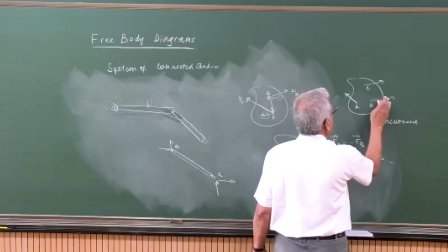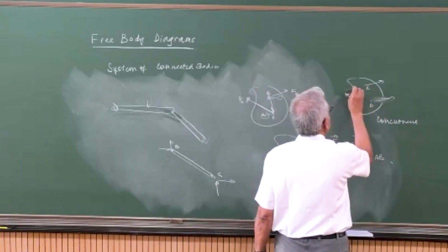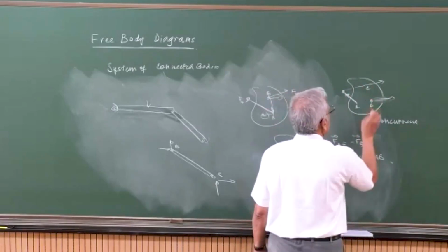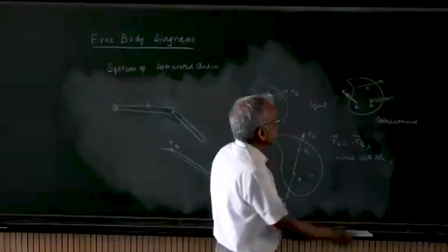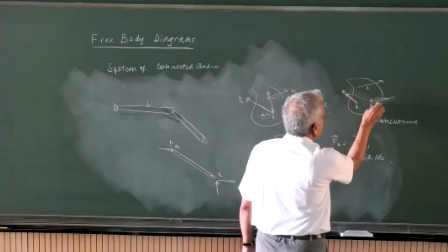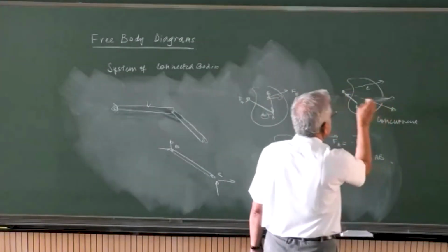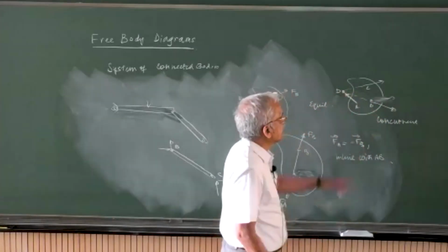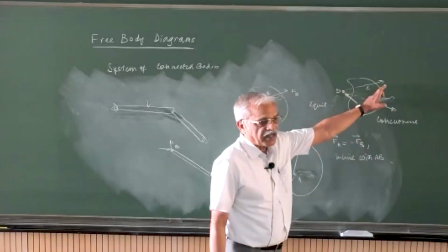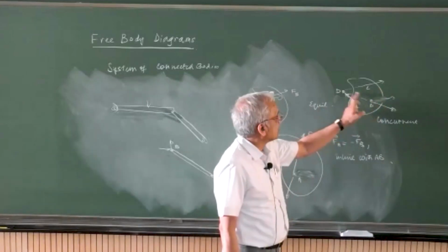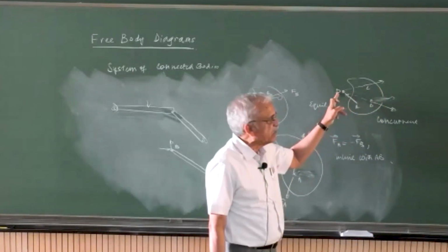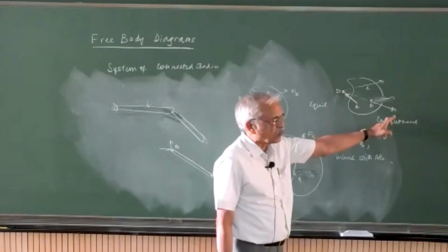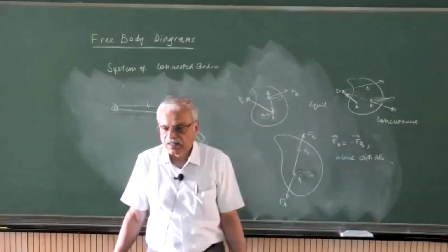For example, if these two are going here, and if you want another force at B, the only chance is that it should be in the line. So this is some line, point D. Okay. So if you know FA and FC in these directions, produce them where they meet. And then from that point D, you draw along B so that you get a force FB.